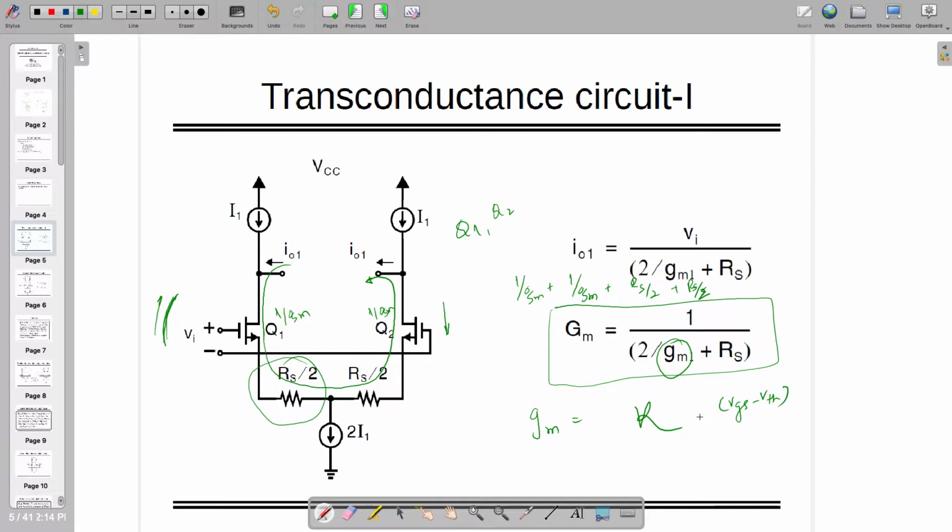So how you are taking this, it's the most important part. What part you are considering as constant, right? That is what I'm saying. If you are considering W by L constant, no problem. For a constant current and constant W by L, this will be the effect. Your point is correct. You might have three different possibilities, which we have discussed in E512. But if it is not the case, and if you are wisely doing all these things, then you are going to have the linear relationship, right?